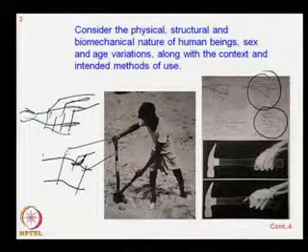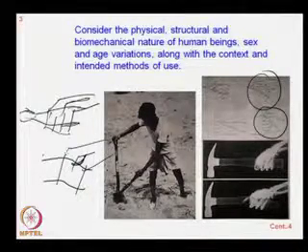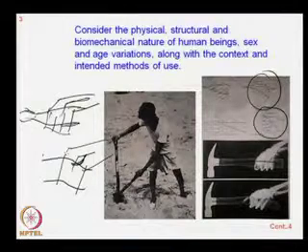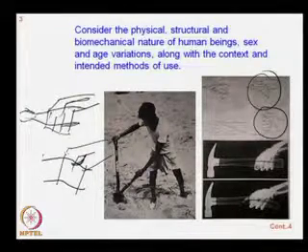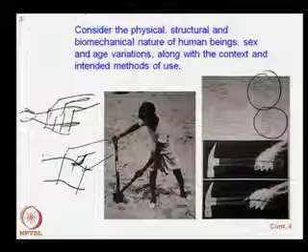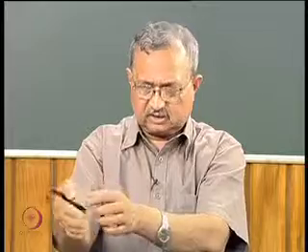Similarly, small hammers are better with a slightly bent handle than a straight handle. If we see our arm and hold it, the holding position and the arm axis have some angle, around 20 to 30 degrees. If we can have this angle at the holding area, it will be easier to hold and operate. It also depends on context-specific applications.